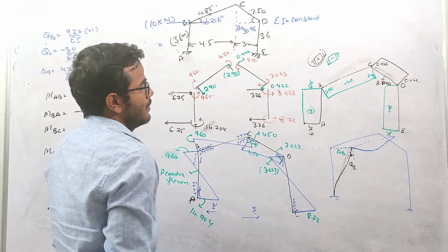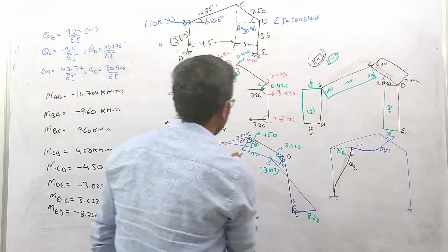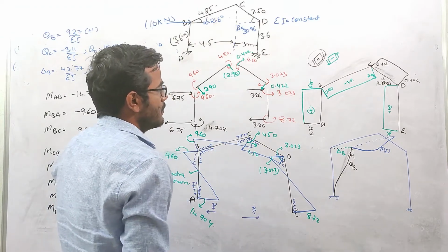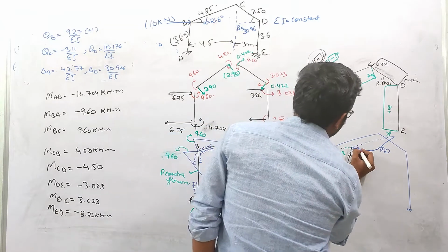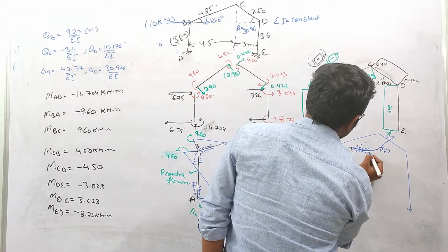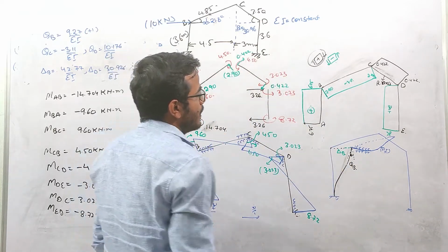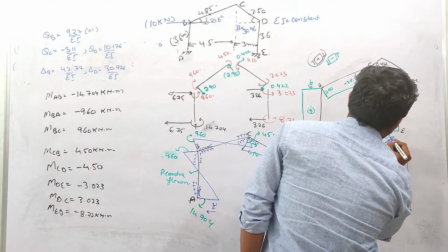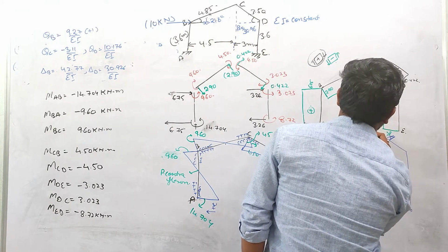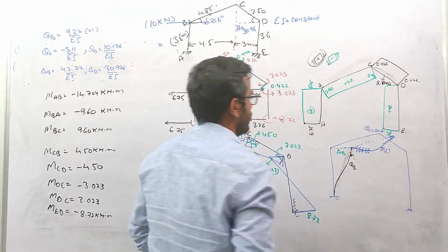Okay, so let us suppose this is our point of inflection corresponding to this point of contraflexion. Okay, this you can calculate. So you can see that this face is in compression. This portion down, this face is in tension, bottom of this member. Okay, so now, and you can see that here the rotation is basically anti-clockwise. So theta c is anti-clockwise over here, right?